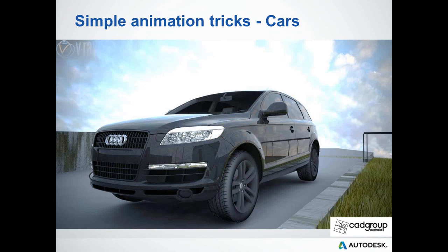If you want to go a little bit further, of course, you can bring in cars. You can purchase more detailed vehicles from websites like Evermotion, and you can add lighting, and you can add formulas to drive the wheels and do different turning circles. So there's the option to do the basic stuff, but there is the option to do more advanced animation with rigging detailed vehicles in special ways to make them interact with the environment.